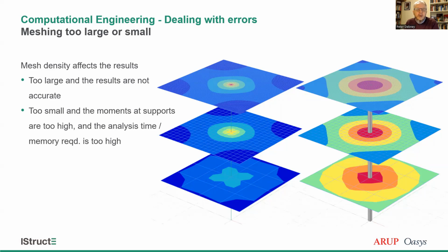And we know the column is actually three-dimensional, the slab is three-dimensional, there will be three-dimensional stresses in that area, but the model is a one-dimensional pin with a two-dimensional piece of paper, essentially, onto the pin. If you look at it too closely, the pin will just punch through the paper. Infinite stresses. You can have these singularities in your analysis model, which are not realistic.